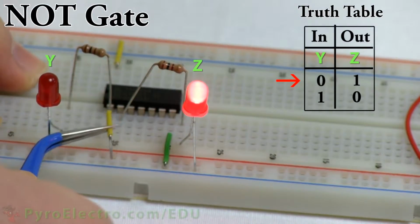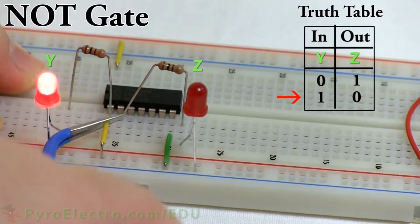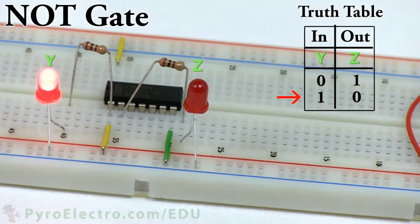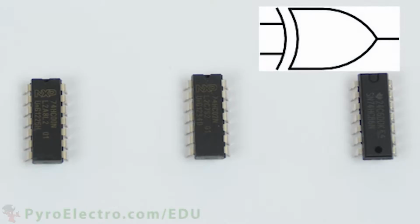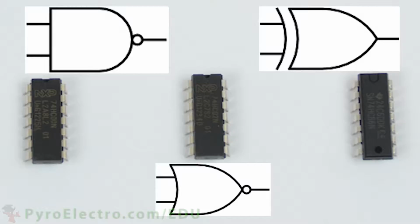And if we change the input to a logic 1, the output changes to a logic 0. Since this 74HC04 is an inverter, it is working perfectly, and we have just verified its truth table. The components kit also includes an XOR gate, a 7486, a NAND gate, a 7400, and a NOR gate, a 7402. Take some extra time and find the truth tables for these devices, and go through and verify that they follow the truth table using the method we experimented with just now.